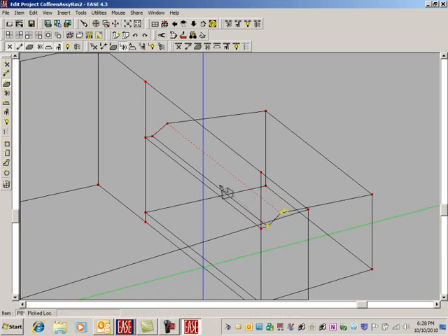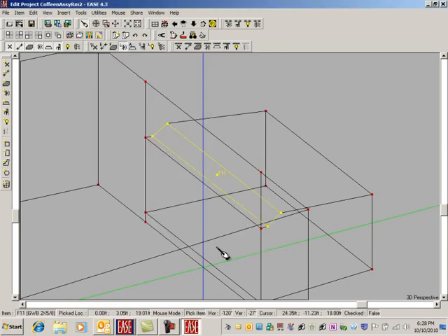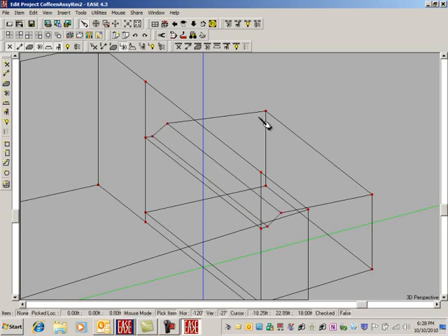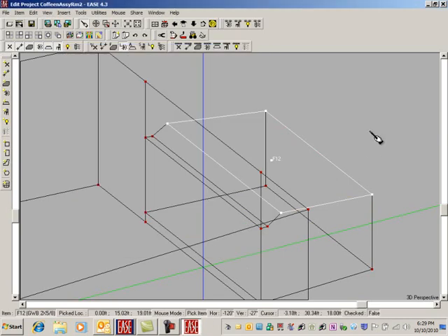Perfect. What we really want to do now is in this same face add one down here. But before we do that, we can get this one straight down here. We could simply duplicate it down here. The window's only 3 feet deep. We could say duplicate, and let's use Cartesian coordinates now, 0, 0, and 0. Let's take it down minus 3 in Z. Minus 3. Say OK. Excellent.